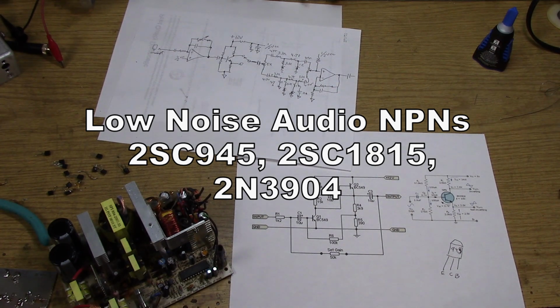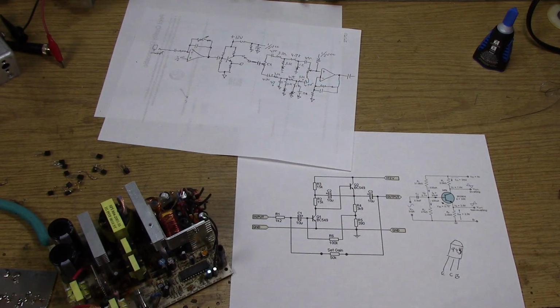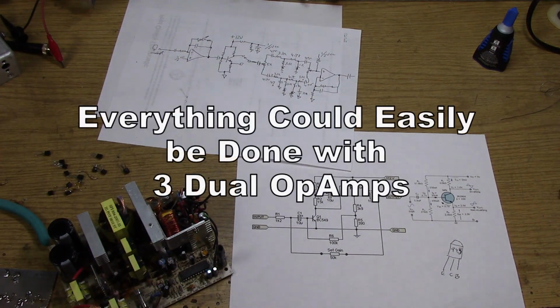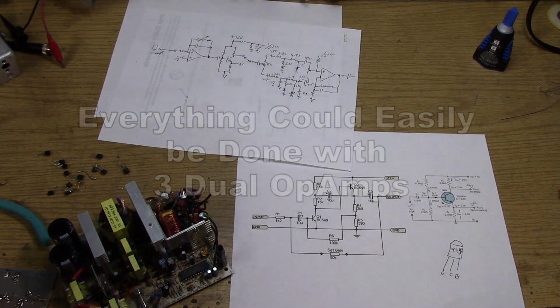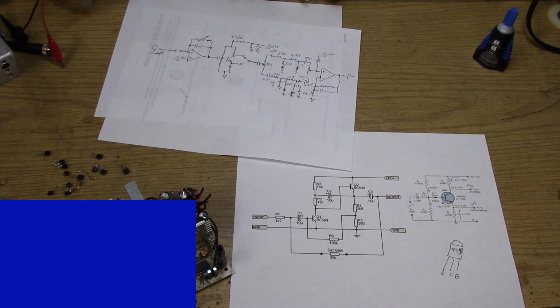The only thing you have to be careful of with this transistor is the pinout is different than the 2222 or the 3904 that you're used to. So with the transistor looking at you, it's emitter, collector, base. So that'll mess you up. But I want to use these transistors out of the ATX power supply to see if I can do all of this discrete. I was thinking of using an op amp at the end. We'll see if I actually use an op amp or not. But I want to be able to do clipping. I want to be able to do phase reversal to get my voice in phase. And I need a little bit of gain and a little bit of shaping.